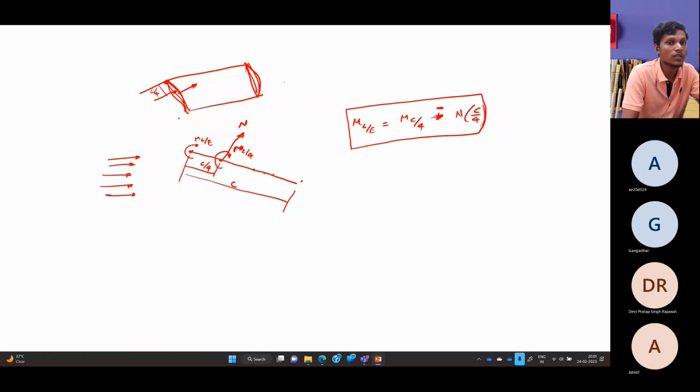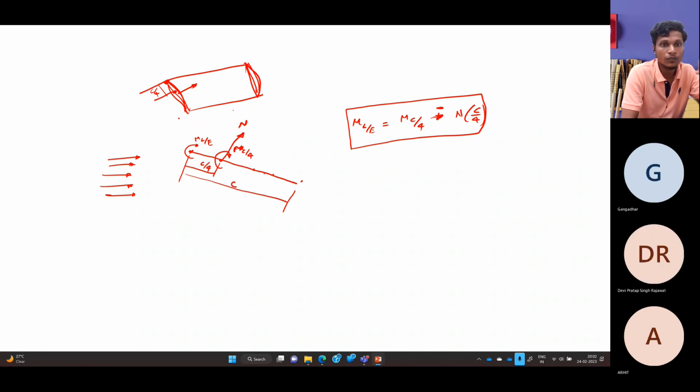Okay, you visualize in an experimentalist way, like this is how you are going to measure the force and moment, then it will be very clear. Moment, force, resolution, everything is only because of your pressure and shear stress integration on the entire surface. You just integrate the pressure distribution and the shear stress distribution, and then see the net resultant forces. That will give you a clear idea. If you directly want to visualize from the pressure to the moment, it will give you a wrong assumption, because it is the net effect of the distribution over the entire surface, right?